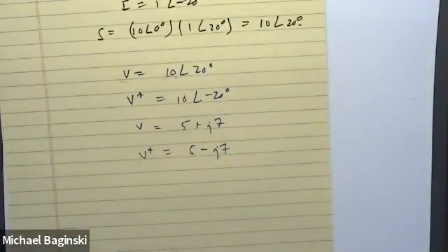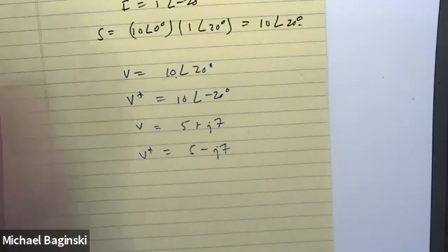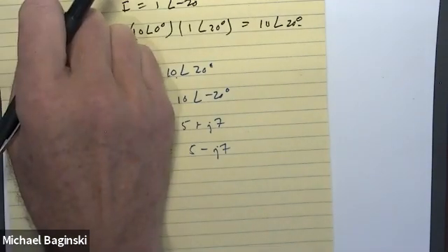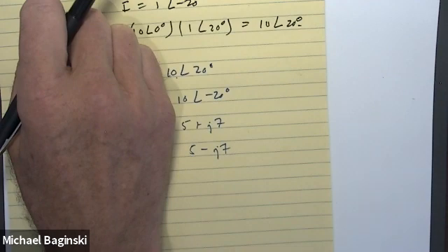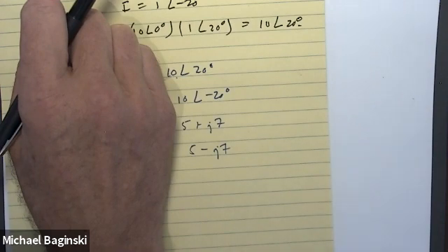So why is reactive power important to us should be the next logical question. Here are two reasons. The first, I'm not even going to write down, I'm going to tell you. The sum of all the reactive powers in a system is 0. So the reactive power supplied is equal to the reactive power dissipated, in a sense. And therefore, if you have 3 of the 4 reactive powers, you can always find the 4th, because you set everything equal to 0 when you add them, and you can find the 4th.